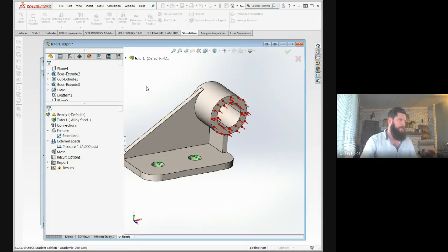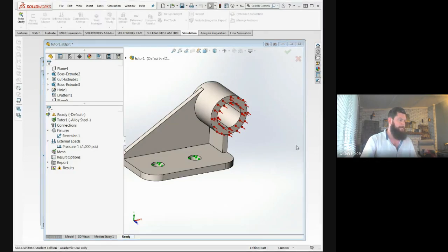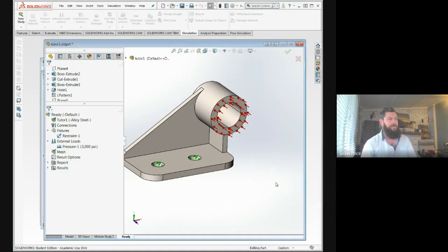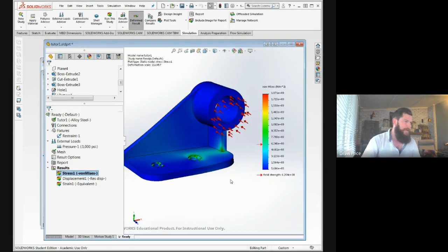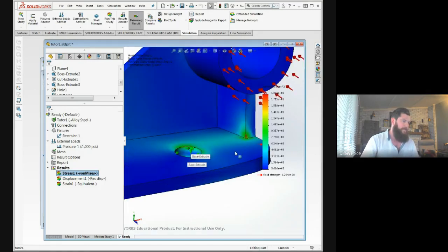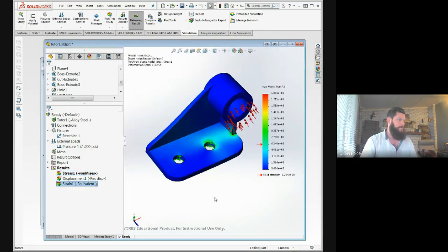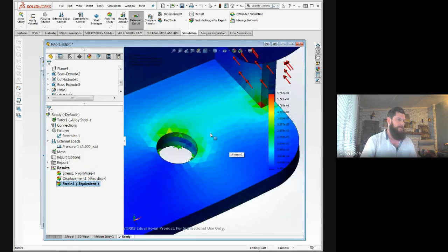So if you were to, for example, remesh this much finer, I'll show you how much longer it might take. Hopefully that works. I'm going to run this now. And when I was running it before, okay, that went pretty fast. So this is a pretty simple simulation. But now if you zoom in on those areas where before I had two bright red diamonds, now they're somewhere in this green area. So there's the strain again. These ones completely went away. There's still one there.